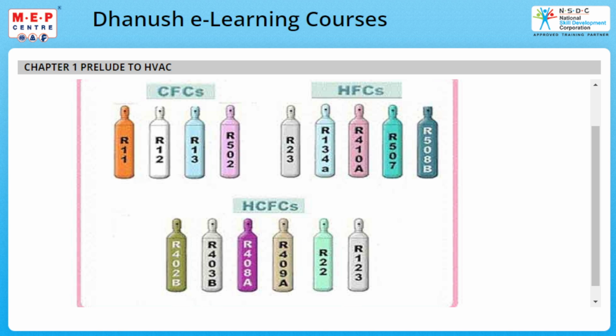HFCs refrigerants: R23 light blue grey, R134A light sky blue color cylinder, R410A rose color cylinder, R507 blue green teal, R508B dark blue navy, R22 light green color cylinder, R123A light blue grey.